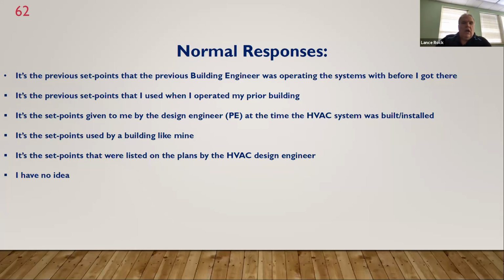Nobody knows what their set points are. So here, how did you come up with your static pressure set point? Here's a normal. It's the previous set points given by another building engineer, given by the design engineer. He could never know that. Set points that was done at a like building like mine, so we're operating at the same static pressure set point. These are all wrong answers. You find out specifically what the static pressure is, and that's what you can do at your BAS system.